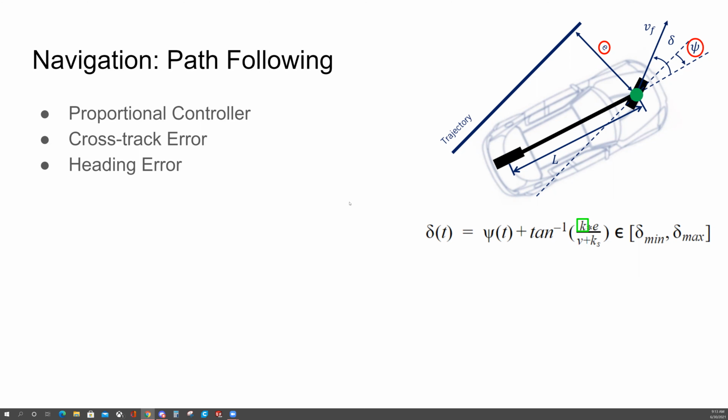The type of control system that we used is called the Stanley Control Law, and it's a path following controller that's very similar to the standard PID control system. However, this one only includes the proportional P gain, so it's just a proportional controller. However, it uses two sources of error to converge our robot onto a path line.